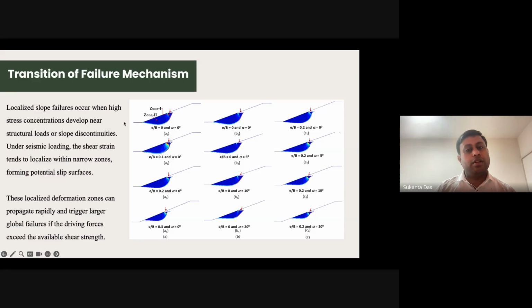In a slope, we can see this is the active zone and this is zone 2, radial, because in a slope it is mostly one-sided failure, and this is the formation of the active wedge. It is not going to be the same as horizontal ground, because the reaction support from the soil mass is highly asymmetric.